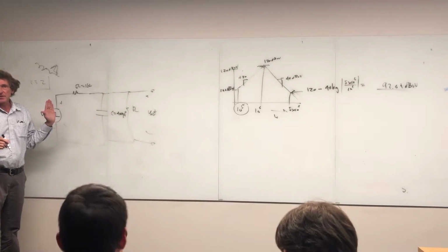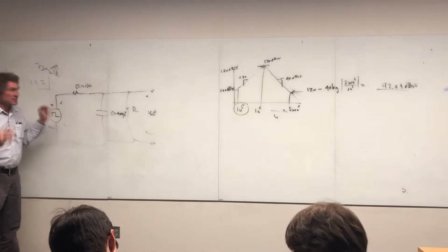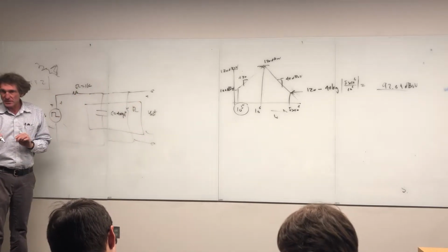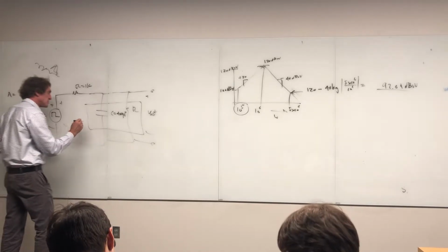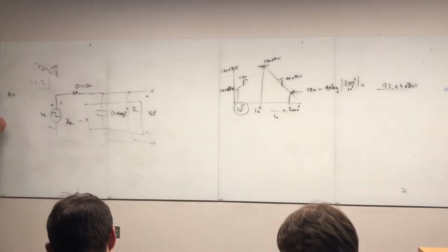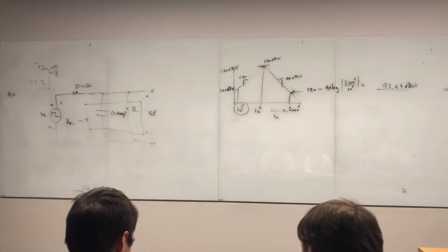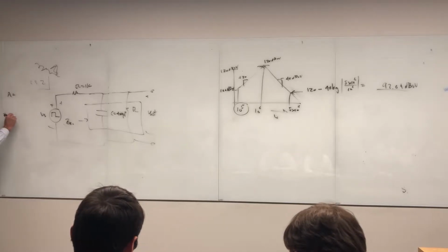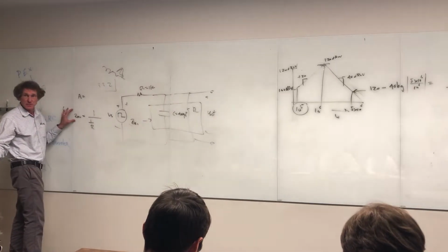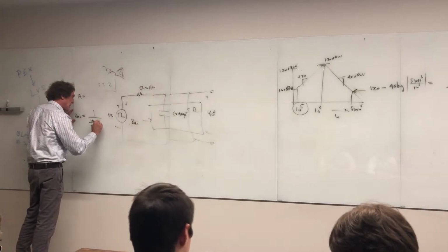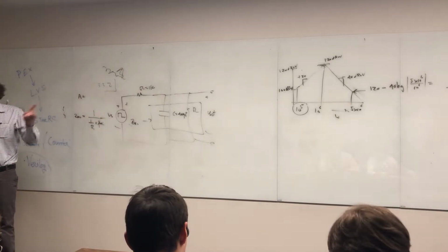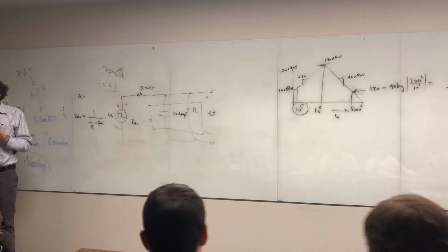I'm going to make sure, I did this before, I want to make absolutely certain you see this. The way I recommend you do it, look at this as a single unit of impedance. And what I usually do is just call this something like ZRC, and then off to the side, just put, does everybody follow me what I'm doing here? Just put ZRC is equal to 1 over R, whatever R is, plus j omega c, whatever that is, right? But omega is going to be 50 omega naught. Follow me? It's the frequency that you end up at.